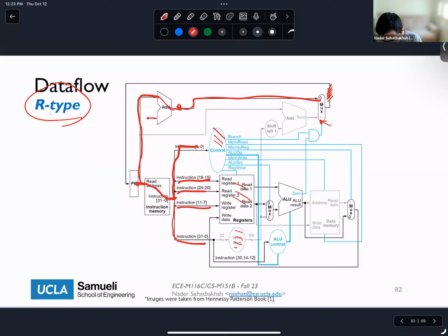So far, here we go. So all these things updated, the controller starts decoding the instruction, takes the opcode, makes a decision. We read two registers, so we get RS1 and RS2 here. We don't need the immediate generator for an R-type instruction, right? But as you remember, I told you that,